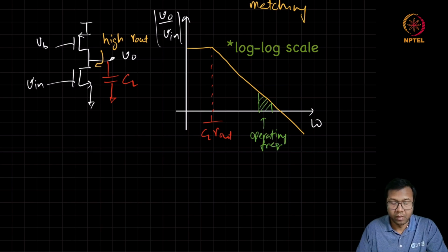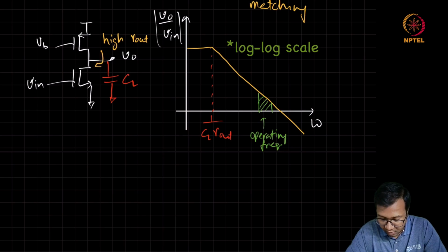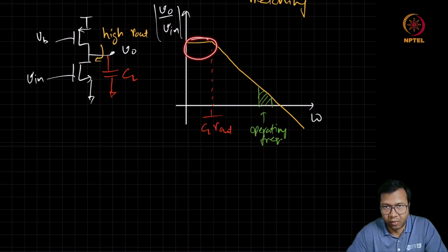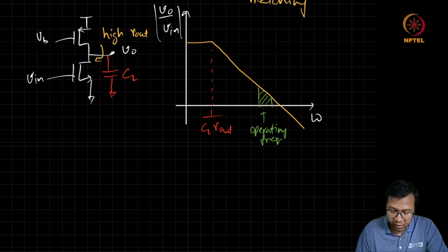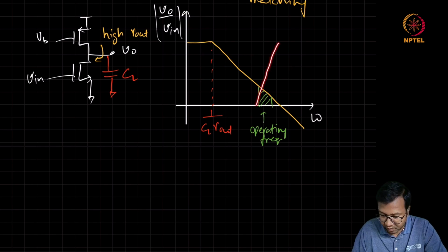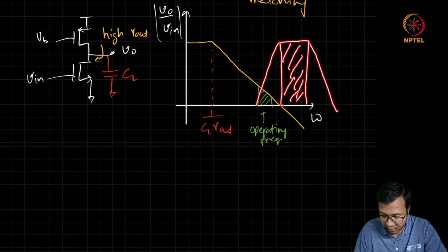As a result of which, if we just take the standard amplifier architecture we know, we are never going to get appropriate gain at the output. So what is done is, since we are limited by this low pass behavior, this low pass response is shifted to a high frequency, so that if we are operating at a higher frequency within this bandwidth, there won't be an attenuation because of this low pass behavior.